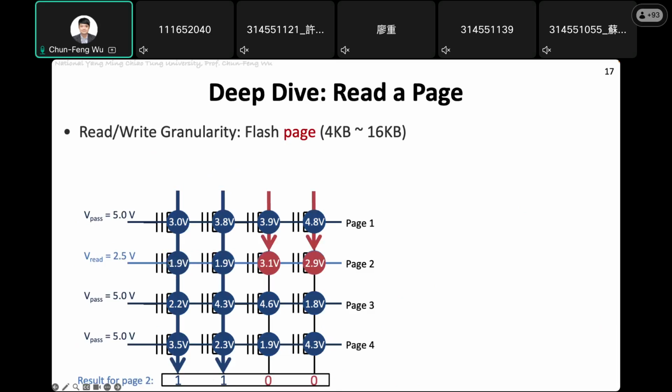So it means we did not actually apply the high voltage beforehand. If we use 2.5 volts, in this case there will be a good amount of electrons excited, so there is a current value. And for this case, because you already applied a higher voltage, some electrons have already been dragged and pushed into the voltage gap. So in this scenario, if you apply 2.5 volts, these cells do not have enough electrons to generate a current, so they will stop here.